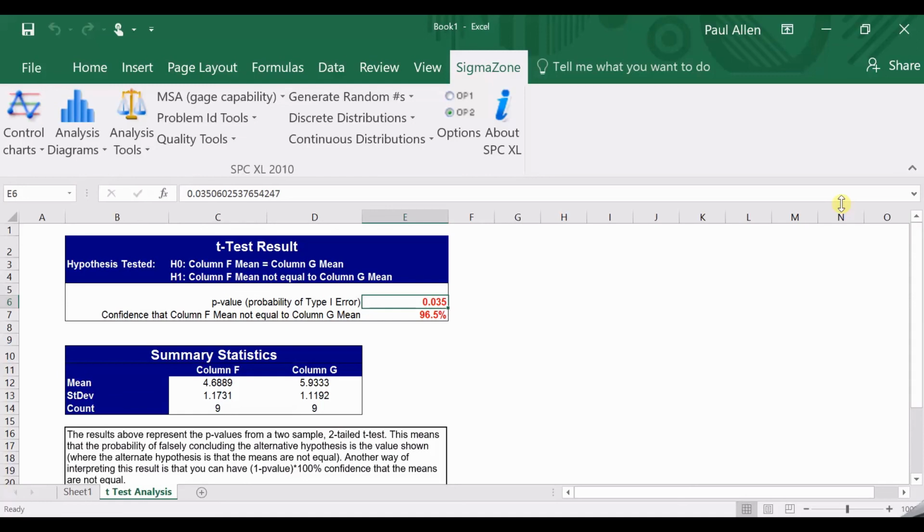It crops up in design of experiments, and that's really where I use this technique. I don't do one-factor testing. One-factor testing, like we've just seen, moving the temperature on its own, is a very slow way to learn how a process works and very inefficient. You won't actually know properly how a process works if you change one factor at a time.